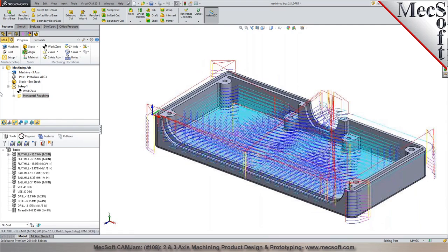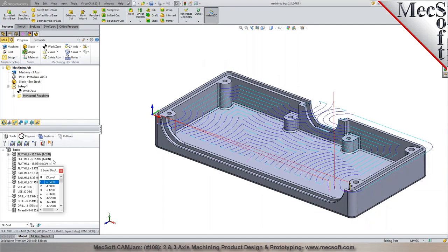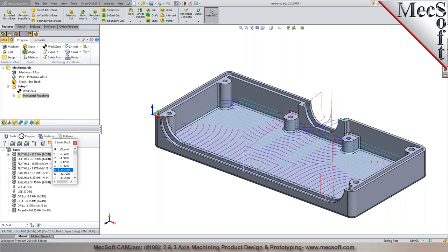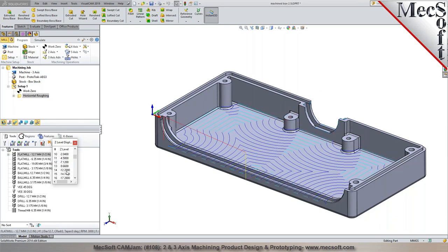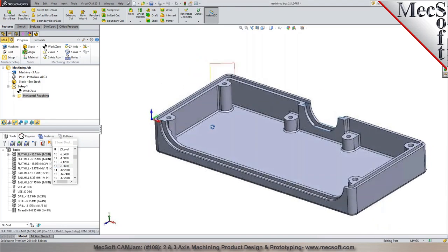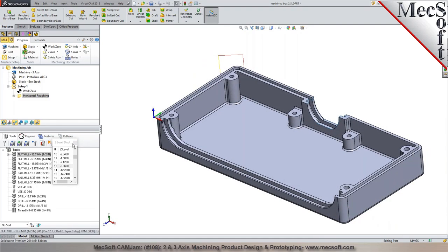So there's your roughing toolpath. It does roughing in levels, and you can see that it automatically identifies core and cavity regions. The cutter starts from the outside and works its way in. And we are doing it in multiple levels. As you can see, it's called Z-level roughing. And it's also cutting around the outside because we did not contain the toolpath to a specific area.